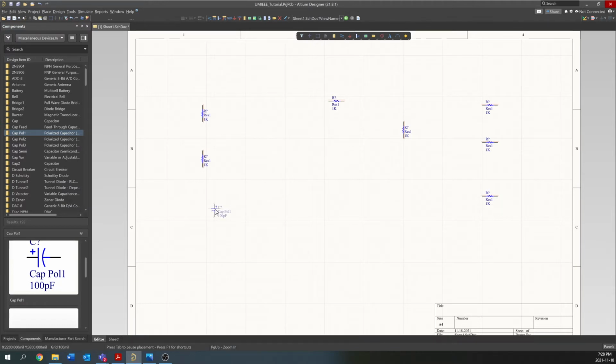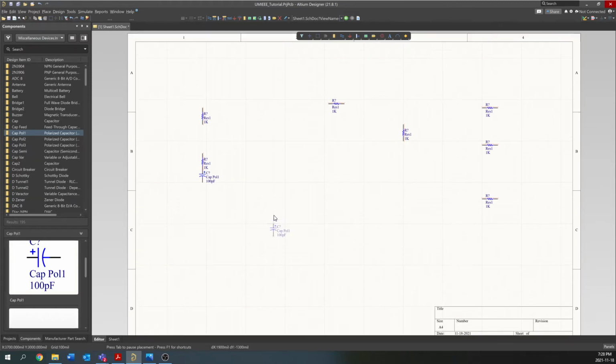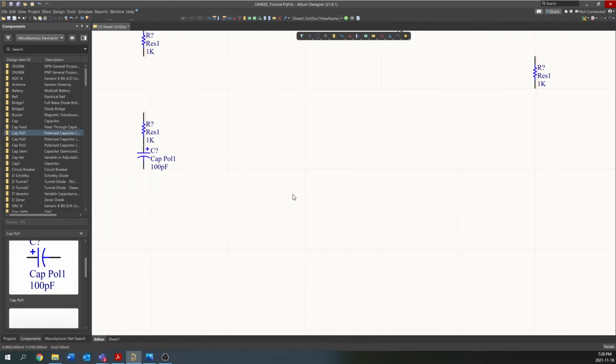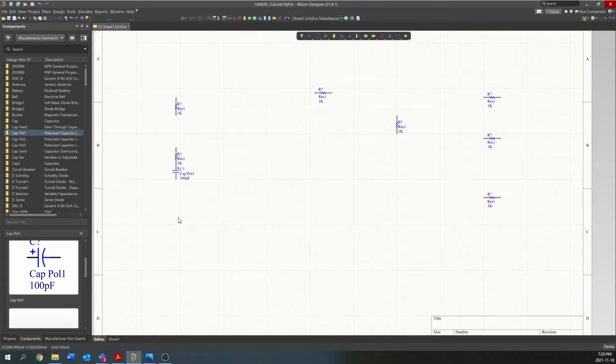When you're routing, in the schematic editor, spacebar flips around the component, and when you scroll up and down with your mouse wheel, the schematic scrolls up and down. If you shift and scroll, it goes left and right, although what we'll be doing right now is placing the component. Left and right, there we go. Left and right, scroll, and then control scroll is zoom. And that is true for both the schematic and the PCB. So there's our one capacitor there.